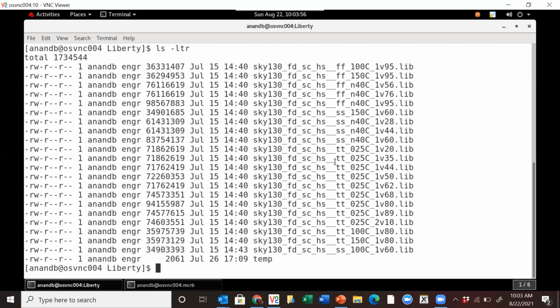In principle, you could have a process corner that is FS and SF and various combinations, but it is very rare to see that. I've never actually seen that, but in principle that is possible. In general, you will see in a standard cell library there'll be .lib files for different voltages, different temperatures, and different process conditions as represented by FF, SS, and TT. So this is what you're seeing here, different .lib files, same standard cell library.